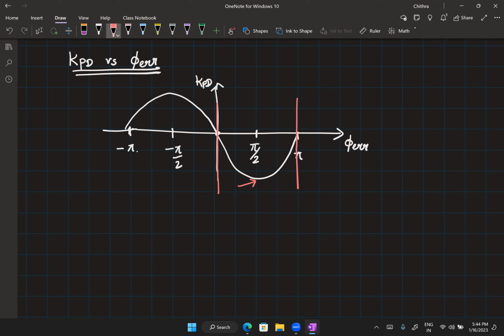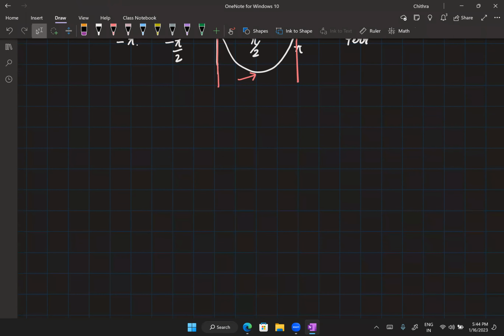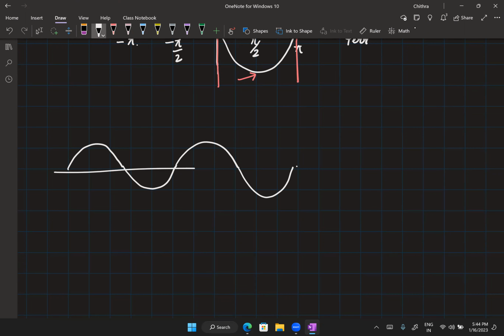Okay. So I know we did a lot of math, but does it make intuitive sense that when you have two sinusoids or two cosine waveforms, the locking point is when they are at quadrature phase between themselves? We saw a lot from the math, but we shouldn't just say it comes out of the math. We should have some feel for it. So if this is my first sine wave, multiplication is? So you're multiplying and then taking the average.